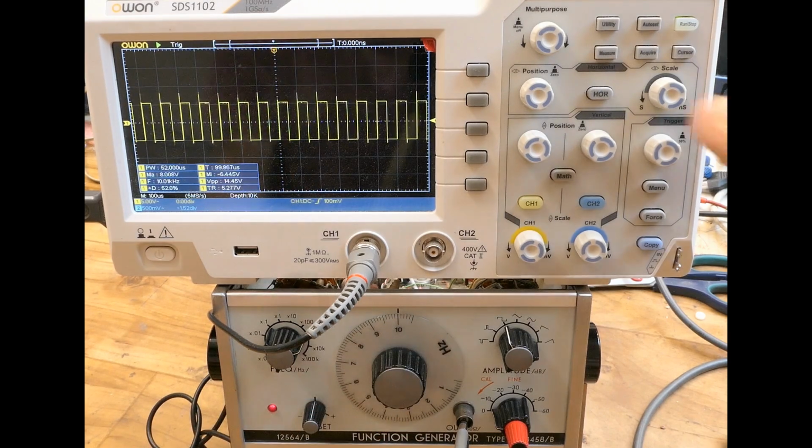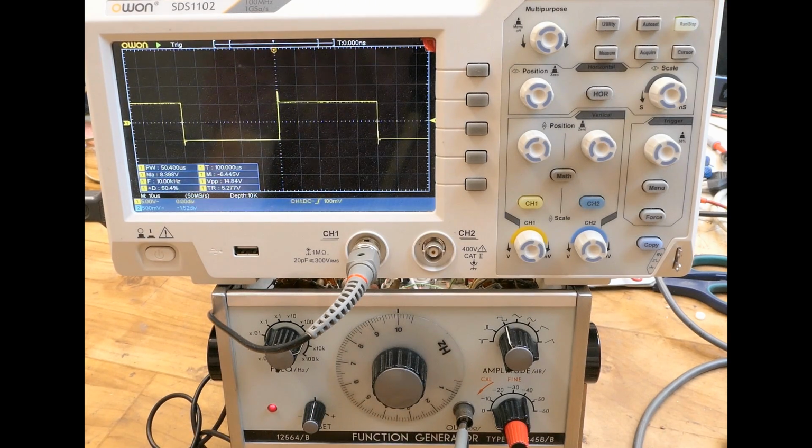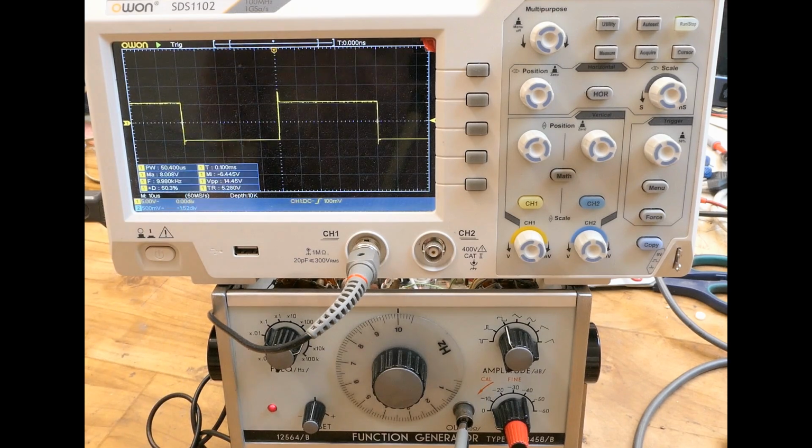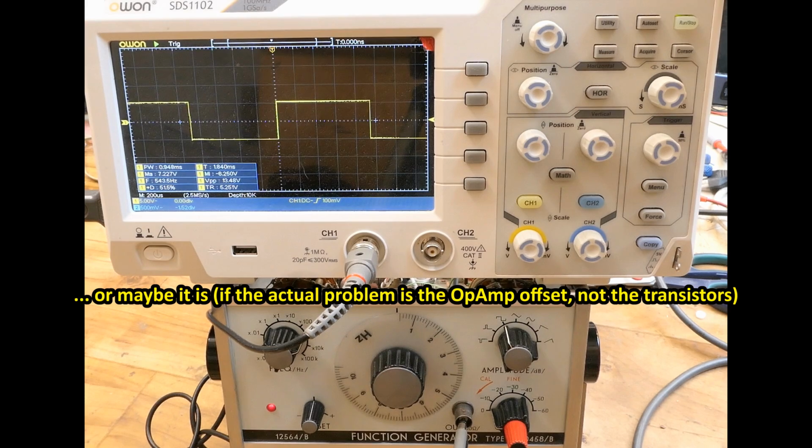On the other hand, at higher positions of the potentiometer, it's less off, because the voltage is higher going into the integrator, and now it's just 50.3%, way less off from 50%. When the voltage going into the integrator is higher, it's not skewed as much by the imbalance in the voltage drops of the transistors. Of course, I can adjust the duty cycle by turning the offset null potentiometers of the OpAmps, but this is not the right way of fixing it.